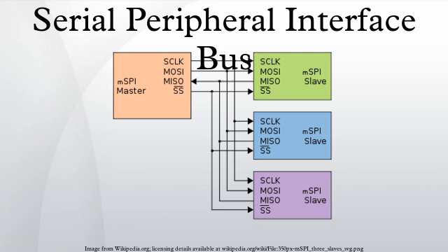Intel Enhanced Serial Peripheral Interface Bus. Intel is currently developing a successor to its low pin count bus that it calls the Enhanced Serial Peripheral Interface Bus, or ESPI for short. Intel aims to allow the reduction in the number of pins required on motherboards compared to systems using LPC, have more available throughput than LPC, reduce the working voltage to 1.8 volts to facilitate smaller chip manufacturing processes, allow ESPI peripherals to share SPI flash devices with the host, tunnel previous out-of-band pins through the ESPI bus, and allow system designers to trade off cost and performance.